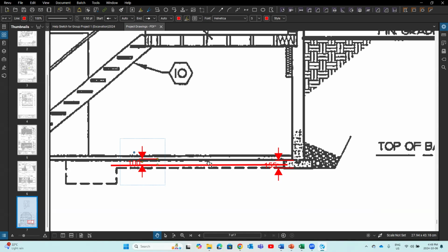So my assumption is, okay, excavate all the way to the bottom of the foundation wall footing. And we are going to make this thickness of the gravel from 100 millimeter to 155. That's my assumption. As a contractor, in real life, I'm going to decide the way I'm going to do the excavation, right? I excavate the whole basement to the bottom of the footing. And the thickness of the gravel, I have to make it, instead of 100 millimeter, now 155. That is my assumption.